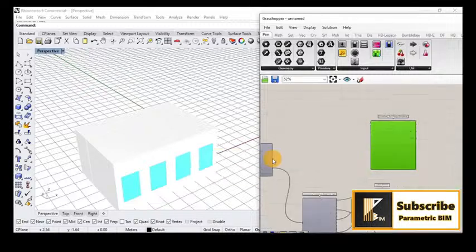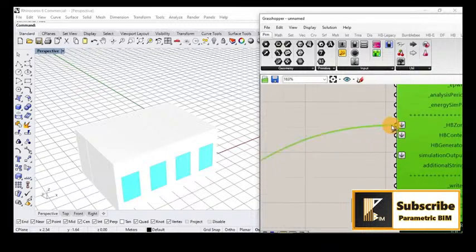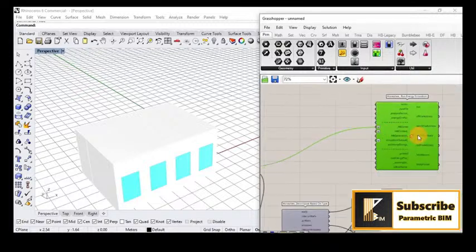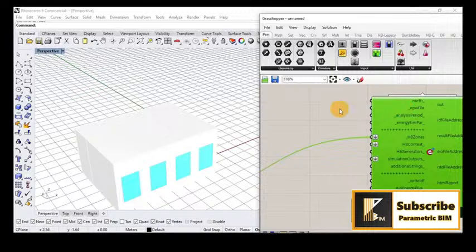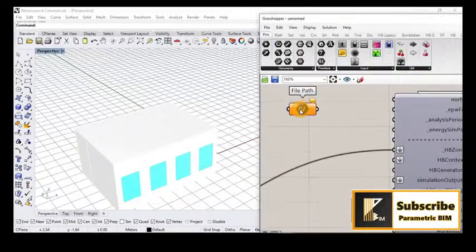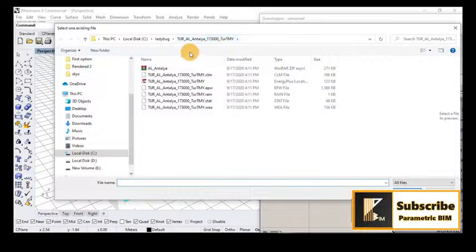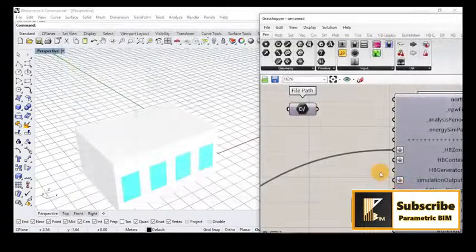So I will connect now the Honeybee zones to the Honeybee zones in the EnergyPlus simulation. I need an EPW file, so I will double click and have a file path here. Right click and set one existing. Maybe I can go with some EPW file here for Antalya city and connect it to the EPW file here.